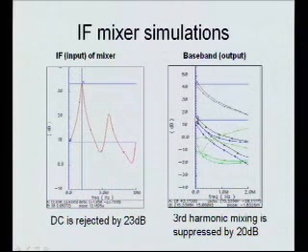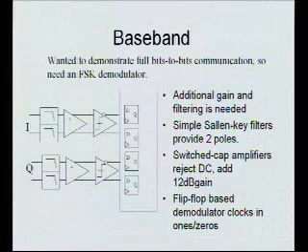And you can see they're down from the fundamental by almost 30 dB. And if it was a pure square wave, they'd only be down by about 10. So we're getting about 20 dB help. And then there's even harmonics down here. So it works in simulation. I'll come back to measurements in a moment.